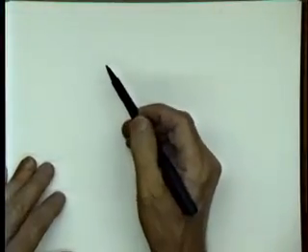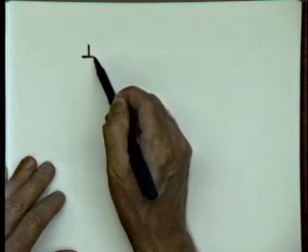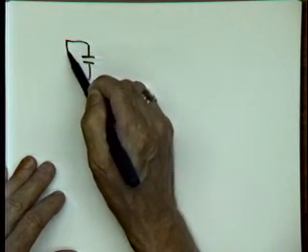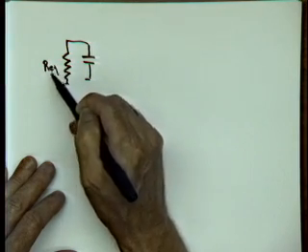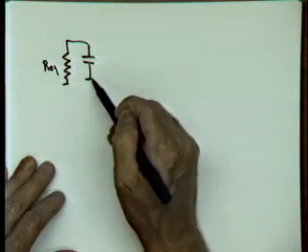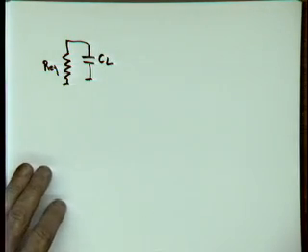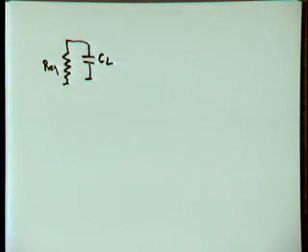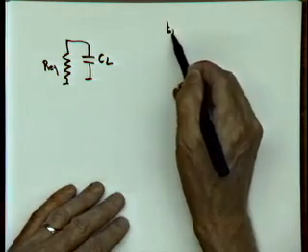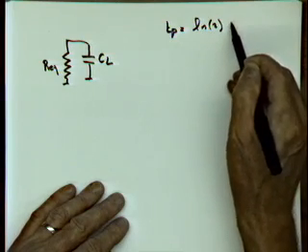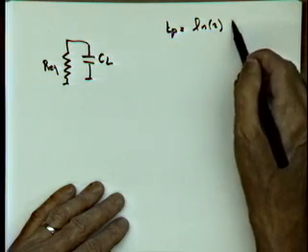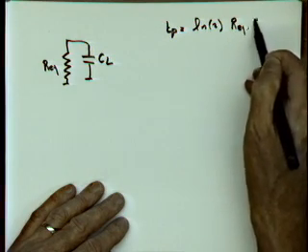Well, now, instead of assuming that I'm going to use a linear current source, I'm going to replace my transistor with a linearized resistor, R equivalent. Okay? And this is, again, CL. Now, for that circuit, we can compute the propagation delay quite rapidly. Tp is going to be equal to ln2 times R equivalent times CL.